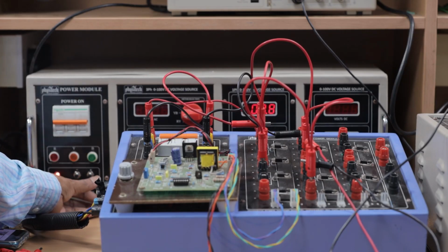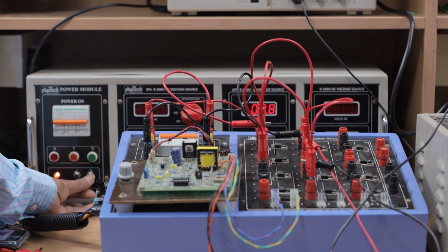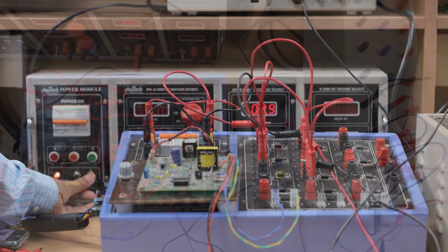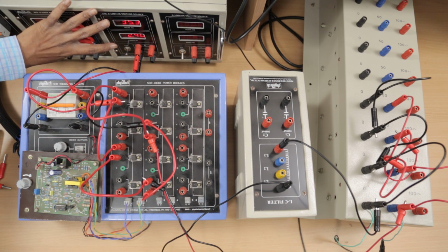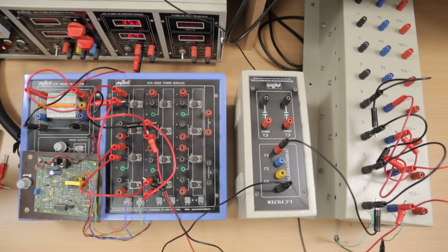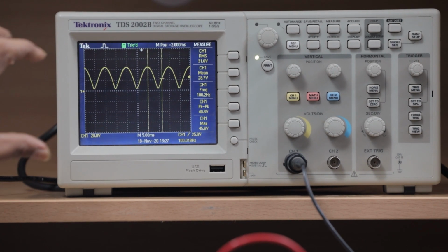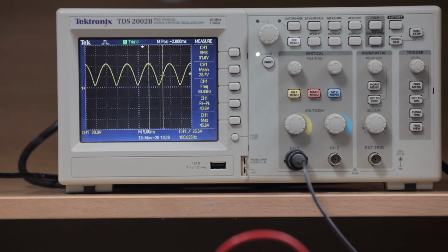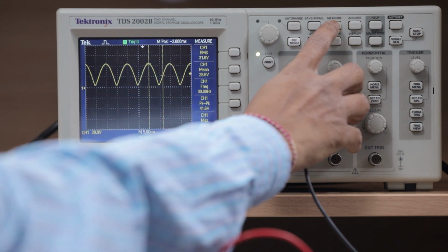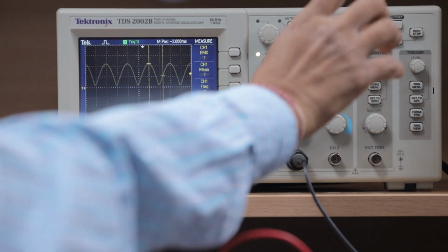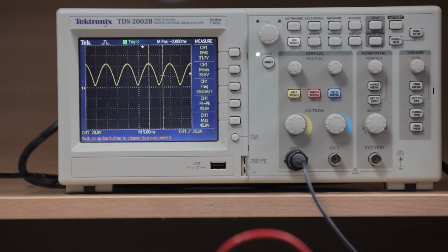Now slowly increase the voltage to 35.3 by pressing the plus button. Now we have adjusted the voltage to the circuit to 35.3. This is the input side current, and you get an output voltage across R and L when firing angle is 0. From this waveform you will measure the mean and RMS voltages, press the measurement button, and this waveform you have to capture in the PC.